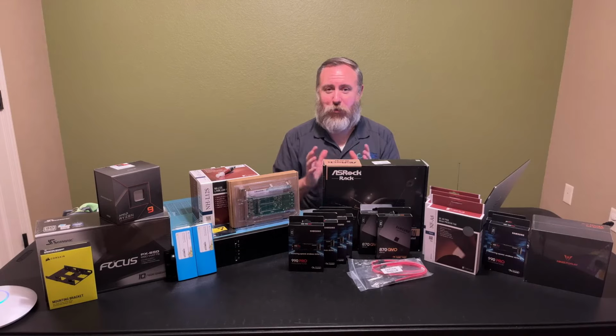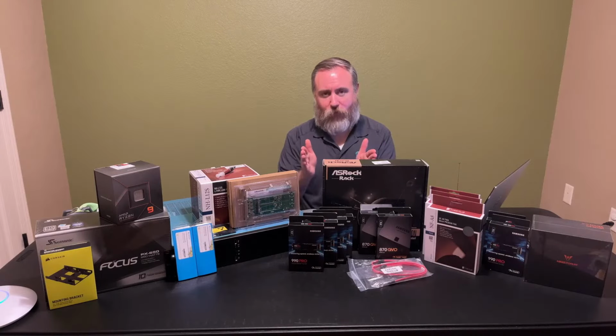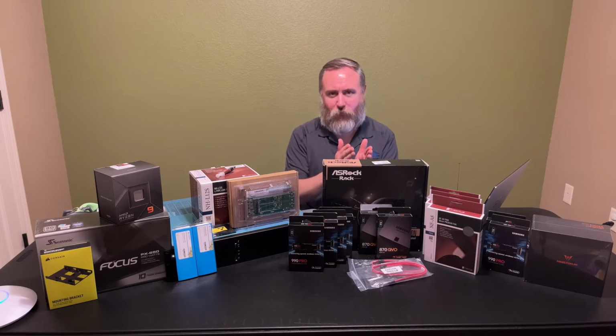So what you can do is, if you buy a motherboard that supports bifurcation, it takes that 16x PCI Express slot and divides it up into either two 8x slots, if you will, or four 4x slots. It's still the same physical slot, but it divides those PCIe lanes. So the 16 lanes are divided into four sets of four lanes.